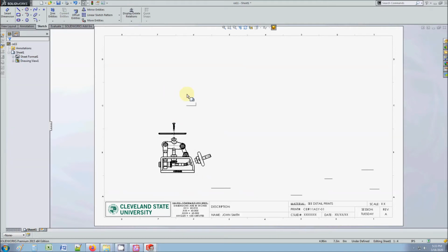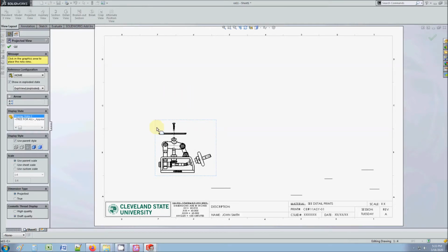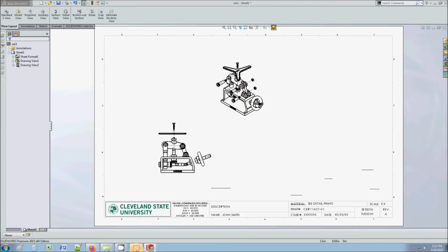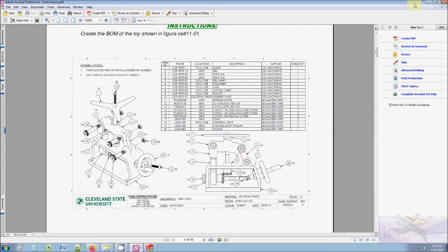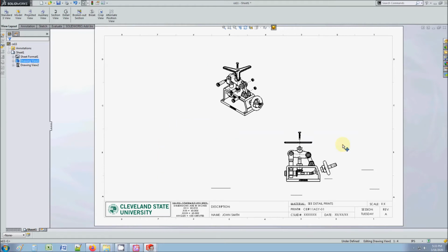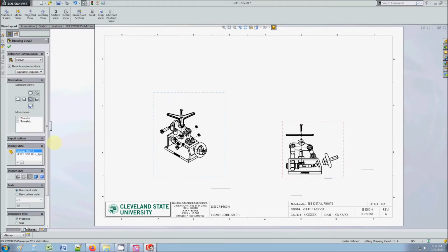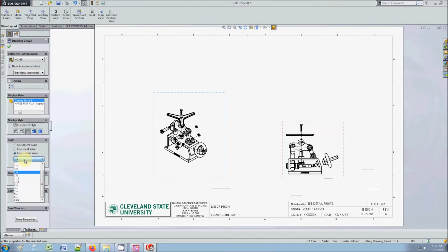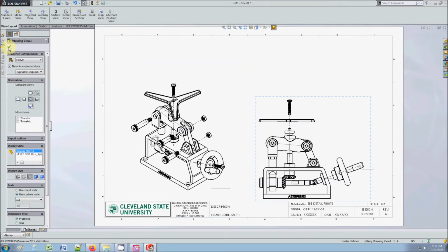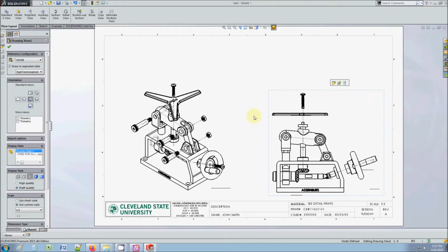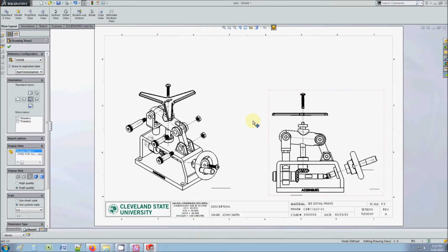Alright. So now I'm just going to create a projection. And I'm going to try to follow the projected view on the diagram here. So we have side view and isometric. So yeah, it looks pretty good. Just like that. And then this is going to be 1/2. And 1/2 for this one as well. I probably should use sheet scale of 1/2. I shouldn't customize the scale for each of them, just to stay consistent.